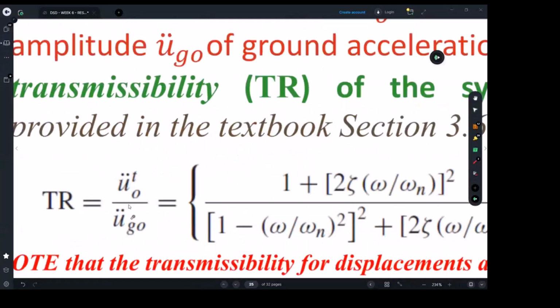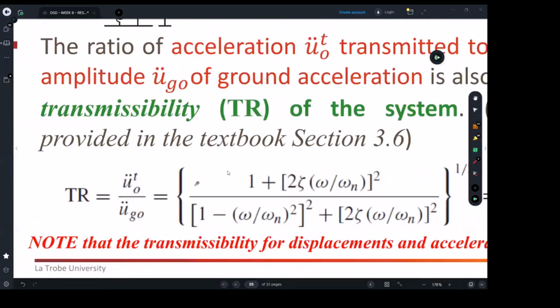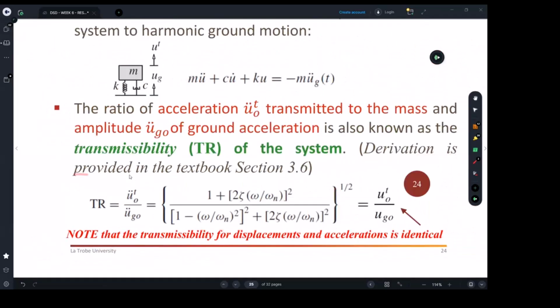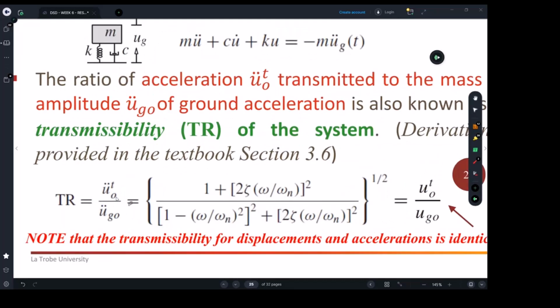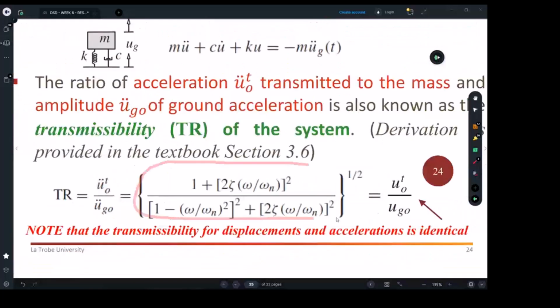And in order to measure the dynamic acceleration resulting on the vehicle, the math that is solved and provided in the textbook showed us we can relate the ground acceleration with the dynamic total acceleration on the vehicle, or that single degree of freedom system, with such a lengthy relationship. So this is a relationship you can use and apply to solve different examples.